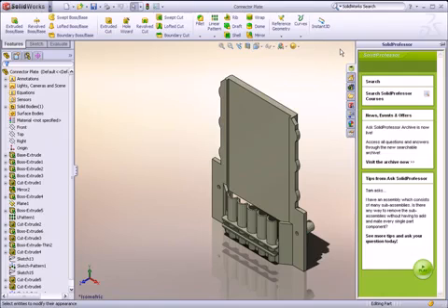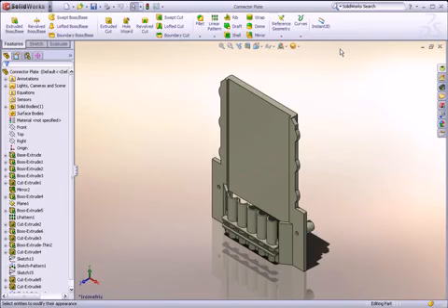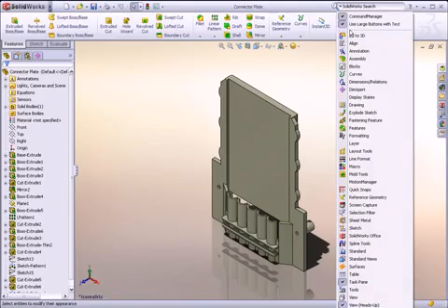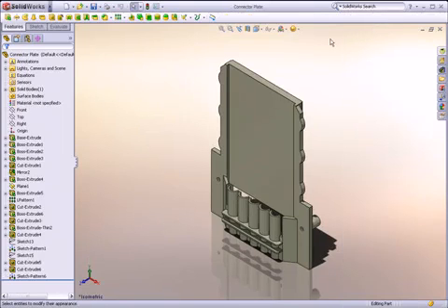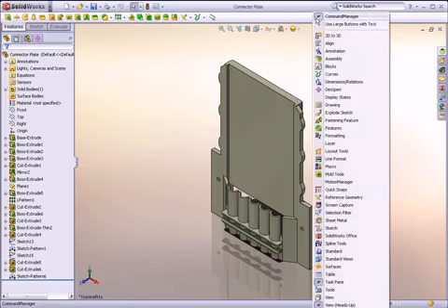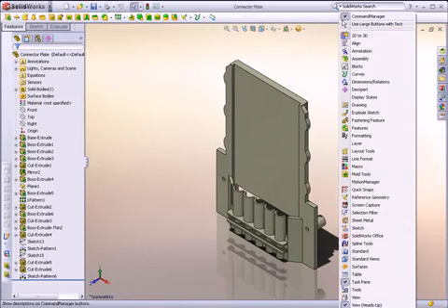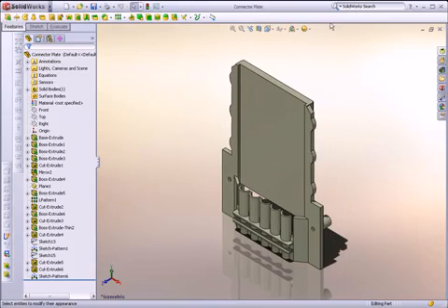By default, SolidWorks shows you a text description of all of the tools on the toolbar. After you've been using SolidWorks for just a little while, the icons become second nature, so you can save space by right-clicking and turning off the large buttons with text. Any toolbars you often use can easily be added by right-clicking anywhere on the toolbar and selecting the toolbar you want to add.